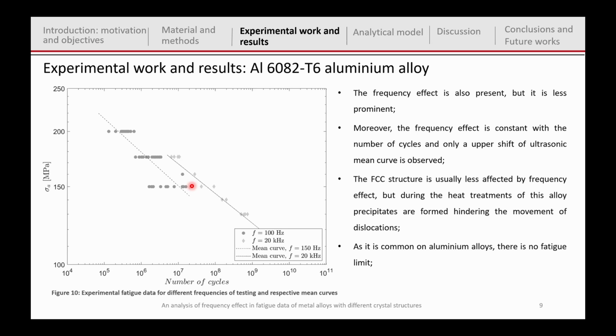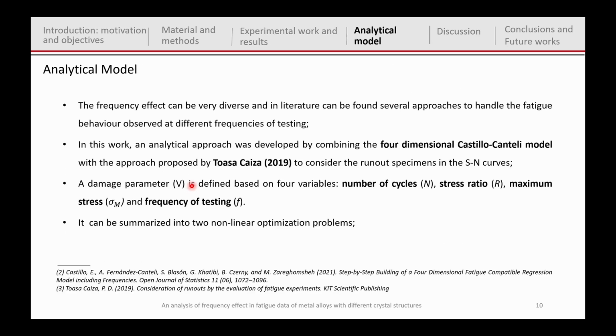So at this point, we thought that we needed to apply a model or an approach to handle the frequency effect, to obtain a mean curve, a probabilistic curve, something that we could use to analyze the fatigue behavior of a structure. And for that, we considered the four-dimensional Castillo-Canteli model and combined it with the Toasa-Caiza approach. I'm not going to detail these approaches very much because they are a bit complex. You can see here the reference to check these models.